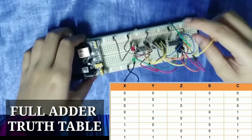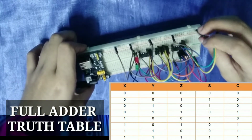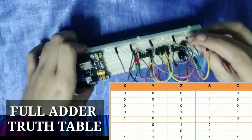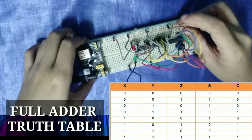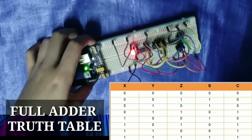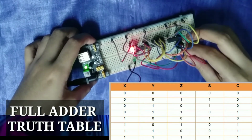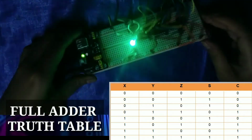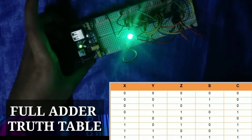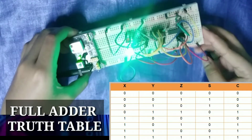Now, if the Y input, the green wire, is connected to the VCC or at logic 1, and both inputs X and Z are 0, so let's connect them to 0. As you can see, again, the S output turned on, or the green LED turned on.